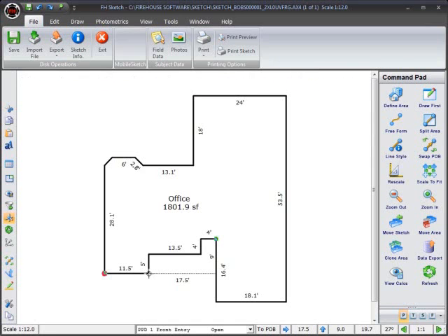I'll draw them by entering the following measurements. 5 feet up. I'll press spacebar after each line to remove the redundant dimensions. 13.5 feet right. 4 feet up. A to autoclose the area. I'll blank the dimension and place the area labels as we did for the office area.